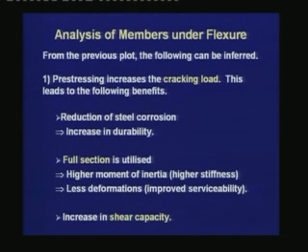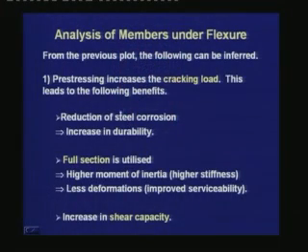Now, from this plot, the following can be inferred. First, the prestressing increases the cracking load. This is the primary reason why we use prestressing in a reinforced concrete section. The increase in the cracking load leads to the following benefits. First, it leads to the reduction of steel corrosion, in effect which increases the durability of a section.